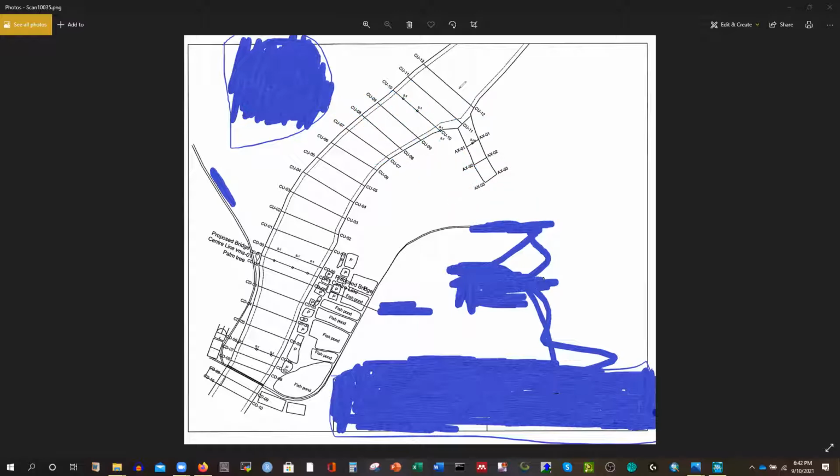The survey company made this plan beforehand. They'll take the cross section here, and this interval is 500 meters, half a kilometer. They made this plan, and then they started their measurement from here.